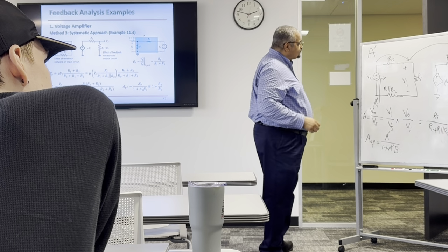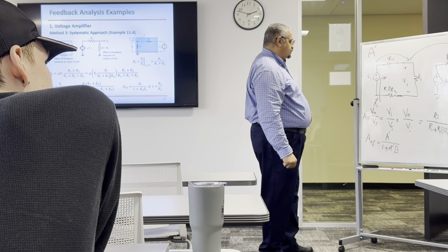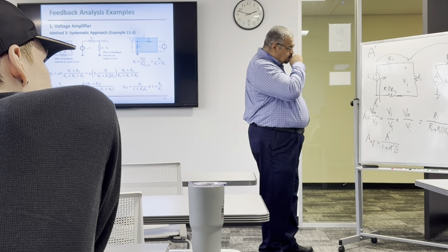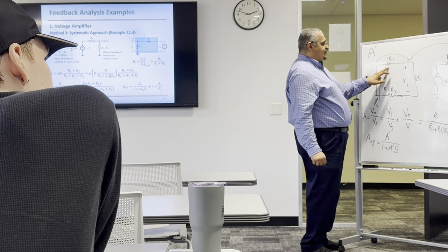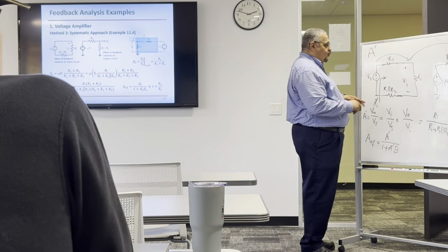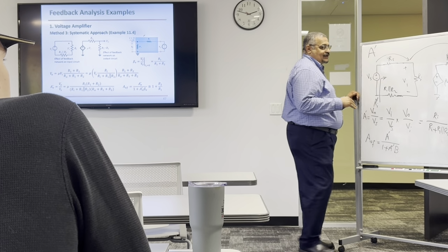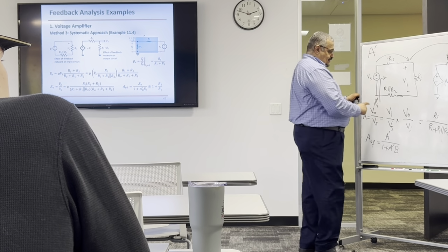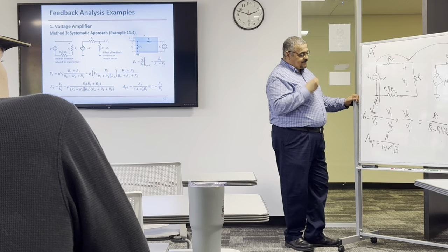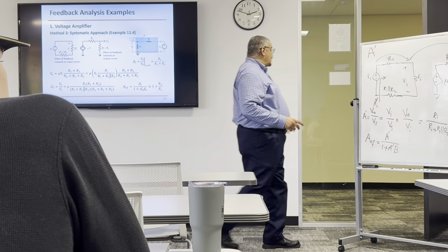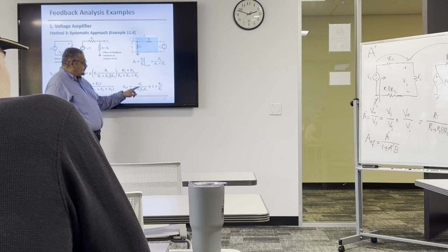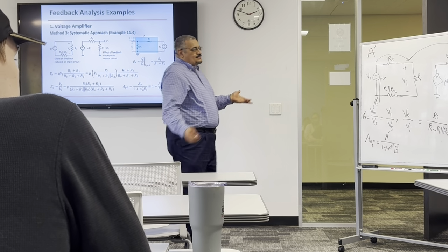Because typically, the way that I think of the input resistance is, you know your source resistance and you're trying to figure out how much of that is actually making it into the amp. Yeah, but if we assume that there is an Rs here, it's going to affect the forward voltage amplifier for sure. So you have to include it in calculating the overall gain and Ri prime. Okay? Because you cannot apply this equation here without including Rs and RL here. It has to be included. Otherwise it's going to be a different circuit, right?